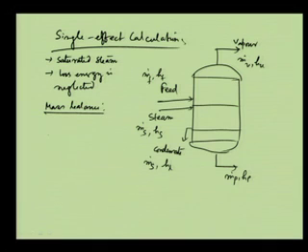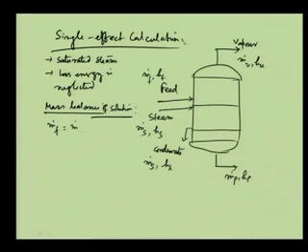we will get m dot F, the feed that is entering in. So, the mass balance is of the solution; that is what is to be done. A mass balance of the steam is not necessary, because we have assumed that whatever steam is entering is getting condensed. What is important is the energy transport from the steam part to the fluid part. So, m dot F is equal to m dot V plus m dot P, the product, and then the energy balance